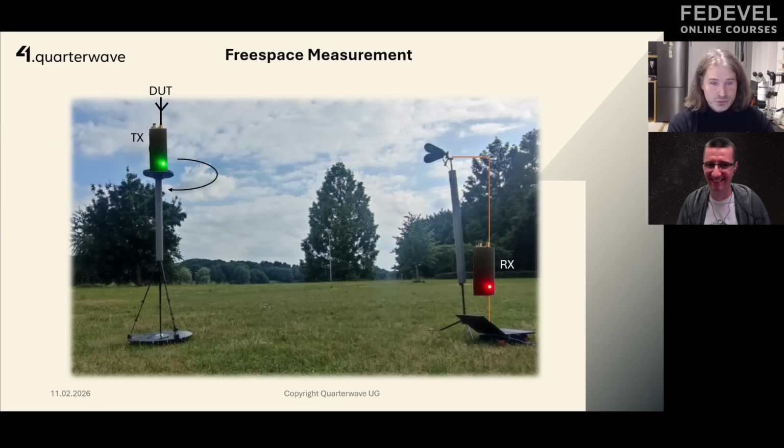What you see is a device with an ESP32, and I have a firmware which makes one a transmitter and the other one a receiver. One is the access point, and the other one is the client. I measure the RSSI, and I have a rotation table that rotates, and I measure the RSSI every 3 degrees. This is plotted to an antenna pattern plot, and then we can see the antenna pattern here.